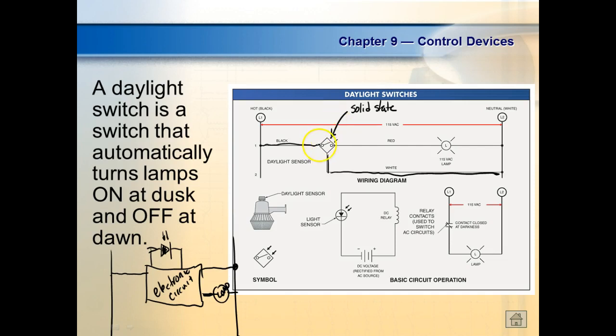So notice, here's the diamond. As soon as I see this, I know this is what? Solid state electronics, which means it's going to have to be powered up somehow, right? You understand that? Then what they do is they just draw a switch assembly in here. Sometimes they'll put the light in, sometimes they don't. Sometimes you have to look that up. So what happens, this powers up the electronics. And then, of course, when this senses light, it's going to electronically simulate a closed switch. There is not a closed switch in there, it simulates them. These things are not going to click. And then what's that going to do? That's going to make the rest of the run become true.